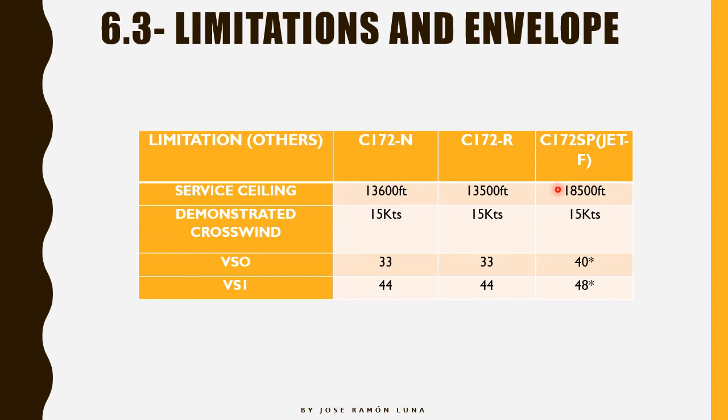These are raw performances, which means you should not rely on this when you fly. From my experience, aircraft usually don't climb that high. Usually the real performance is worse than that. If you climb to 13,600 feet, you might be able to make it, but it's going to take a long time, and probably your airplane is not going to respond too well at altitude. So if you want to try, maybe a simulator is better for that.